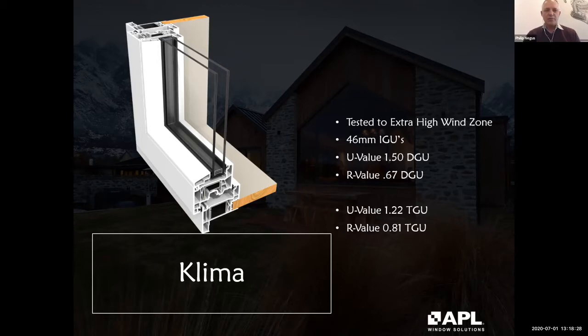They were like the first generation UPVC systems, so they're only like a 3-chamber system. I think now they're up to about 7 chambers. And what I mean by that, you can see the cross section on this Climber product. It's the number of chambers, the air pockets, if you like, from the outside to the inside, which ultimately determines how well those sections are performing thermally. And hey, look, there are limitations around a UPVC system, and I'll cover that a little bit later on in this presentation. We've brought a 5-chamber system here to New Zealand.